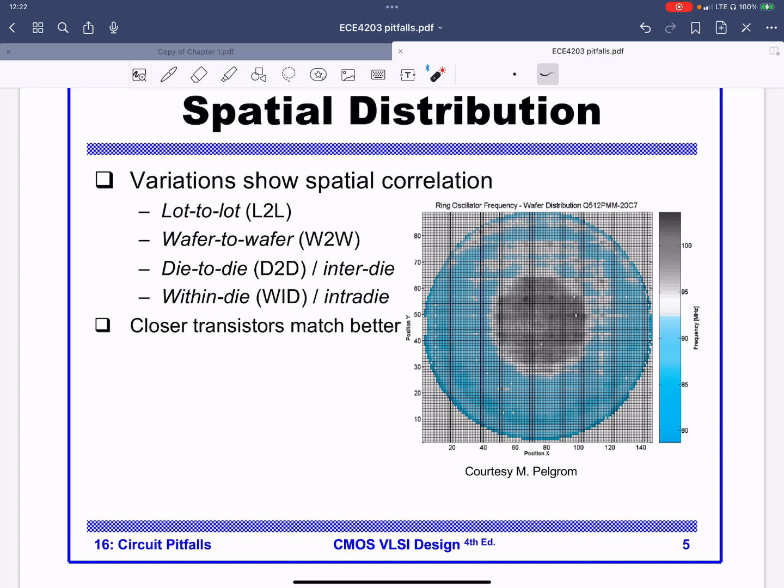You see this sometimes when you see different grades of microprocessor parts. So you'll see some clock, they're selling something that can run at 3 gigahertz for more than something that runs at 2.8 gigahertz. Those are all probably coming from the same wafers. They're just getting cherry picked or binned, in the language of the business, so that you're separating slow from fast circuits. The same thing could happen between wafers.